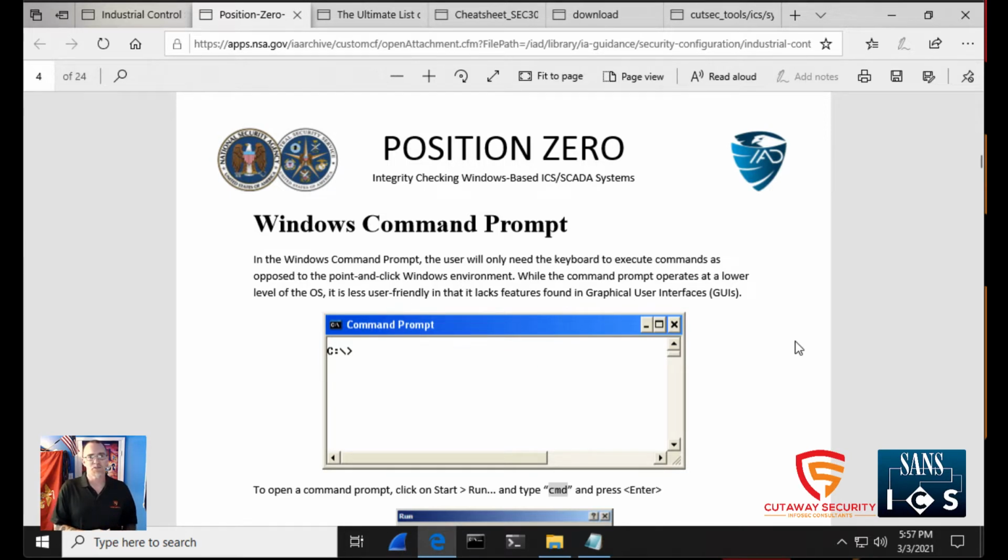Why that's important is because there are third-party tools out there that do this. You can purchase a commercial solution or even download some open source ones, but you have to install it on the system. That can be a problem within our control networks because the vendors and integrators don't like us making modifications to the systems. Even our process engineers don't want new programs on their systems because that can change the behavior, CPU and memory usage, and increase the amount of network activity on the network just by implementing that software.